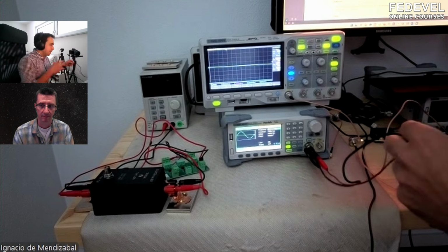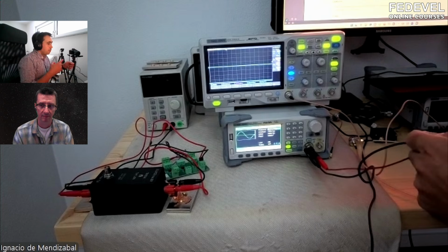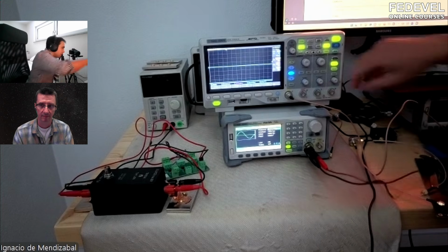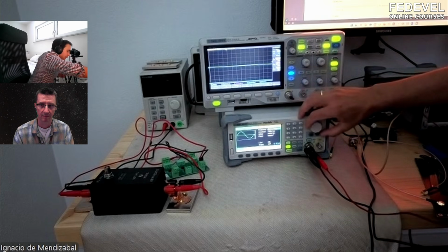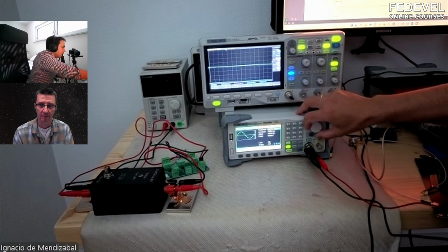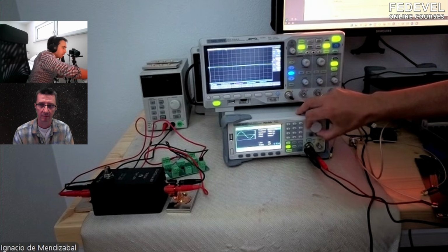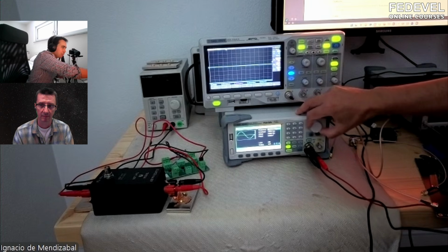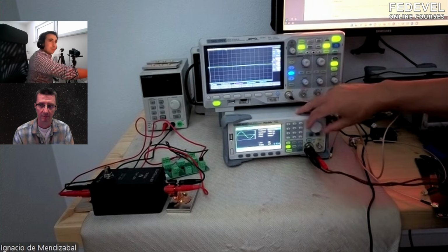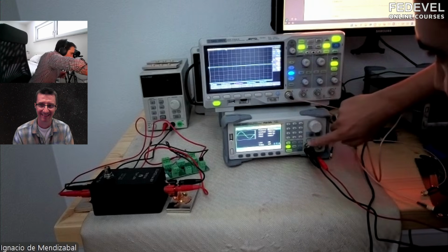And the good thing of this simple experiment is that with a signal generator, you really know what you are injecting. You have a sinusoidal signal, you can inject a square signal. So you really know what's happening there. And what is very surprising most of the time is that some probes don't measure what we expect them to measure. And this is something that we're going to see right now.